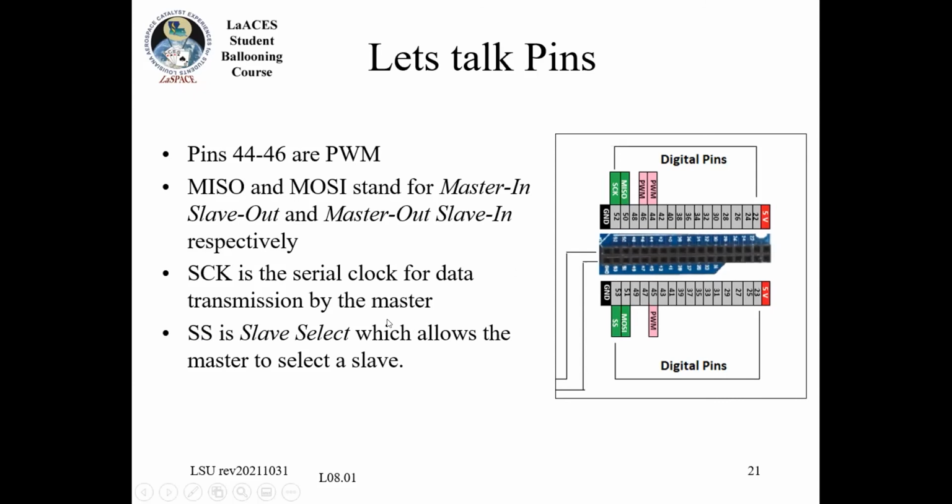In this case, the SCK is your clock pin. The CS or SS is the select pin. If you have multiple devices, you will have multiple select pins. Basically, you pull that pin low to tell the appropriate device, hey, I'm talking to you, as opposed to any of the other things that might be connected on the MISO, MOSI, and SCK pins.